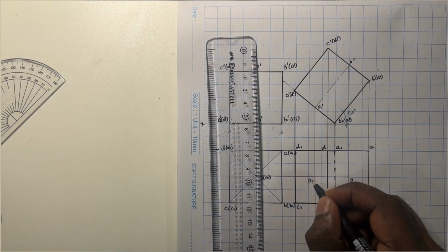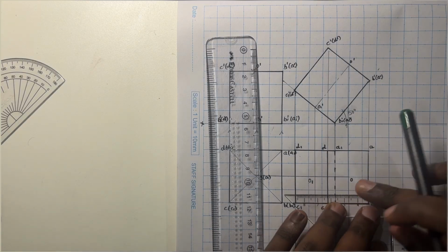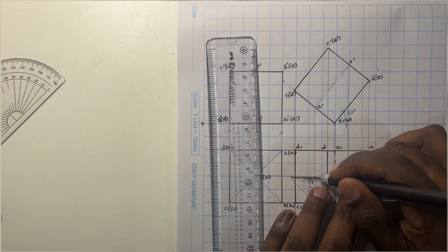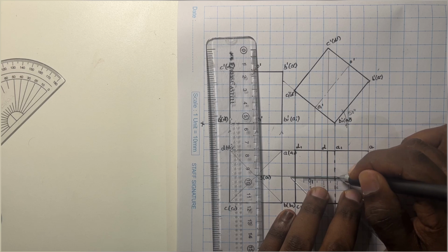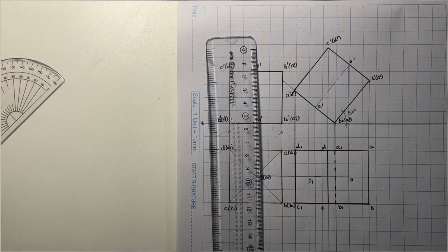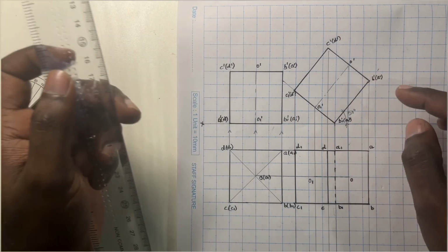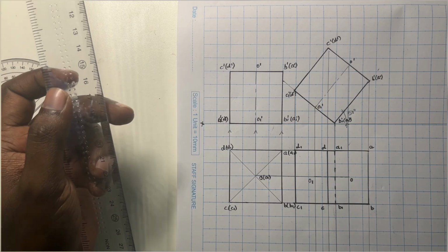So this is the axis point O1. So this O and O1 is the axis point. So let me just show the axis using a different color. So let me just complete drawing the axis line. So let me just draw O1 to O. So this is the axis of the cube. So in the second position, the lateral square face of the edge on which it is resting is making an inclination of 50 degrees to the XY line.